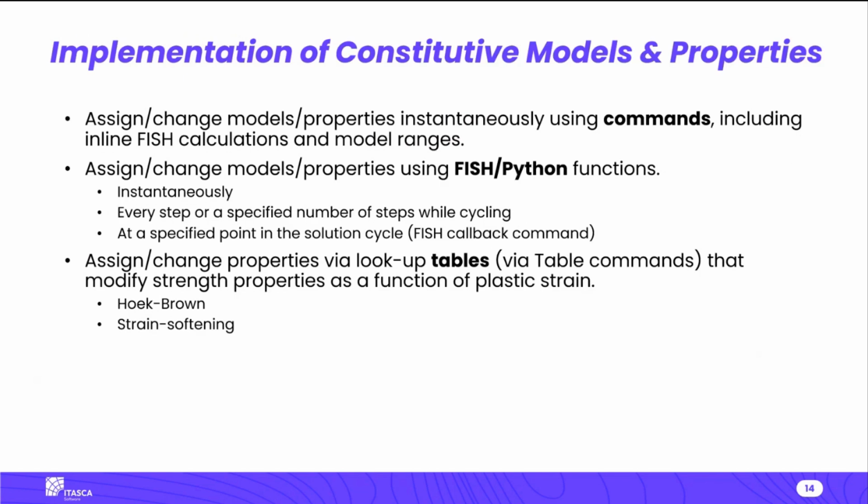Okay, so that's basically the background. Obviously, you need to implement this in 3DEC. You can do it with commands. It's also possible to do it with fish. You can change the constitutive model and the properties using fish if you want to.